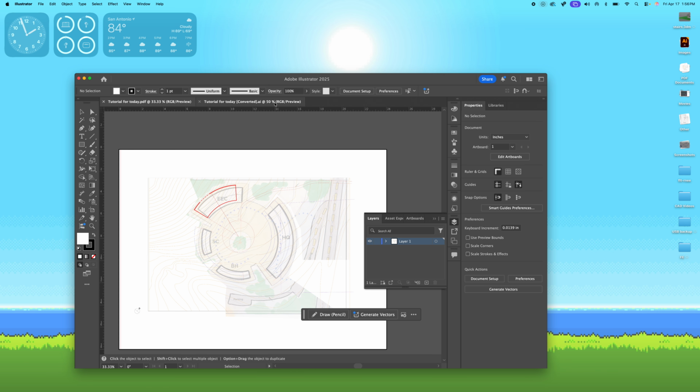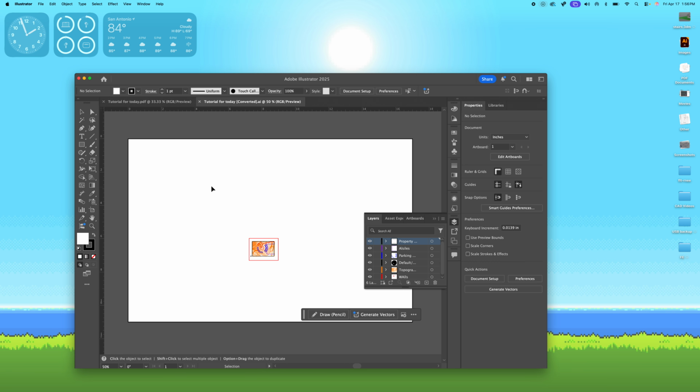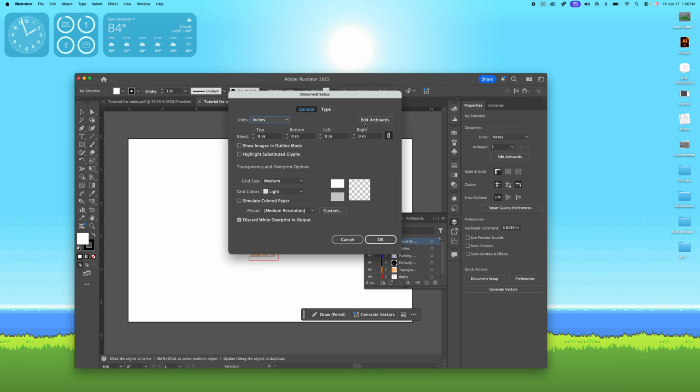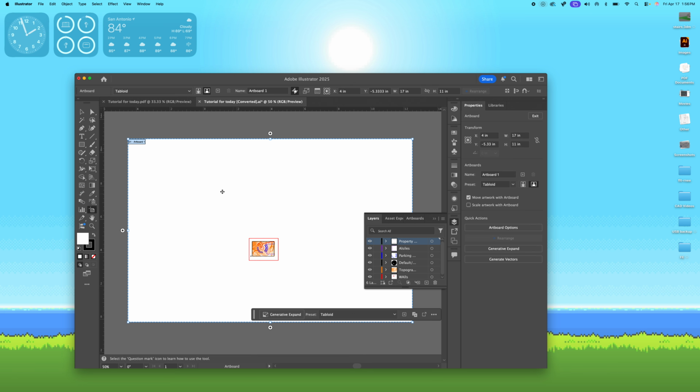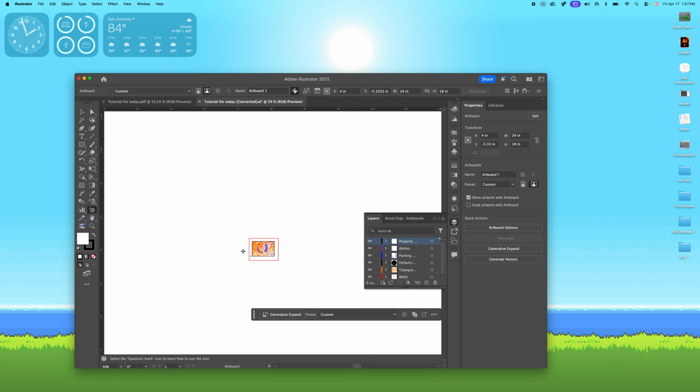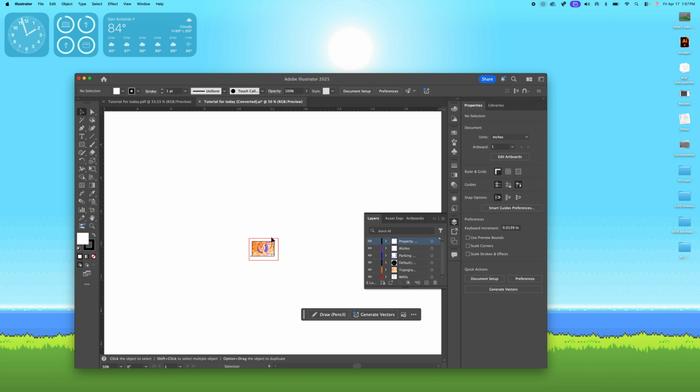Yeah, so that's 24. And in my case, it seems like it just chose a generic artboard. That's okay, because we can change the artboard. We can go to File, Document Setup, Edit Artboards, and essentially click on this artboard and go, oh yeah, it's a 11 by 17. I definitely need something bigger than that. So I'll go with 24 inches and 18 inches, just because that was what I established that rectangle to be.